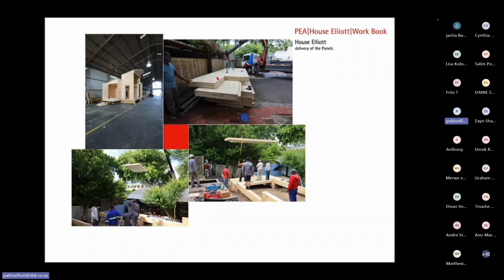So you can see here how the panels are laid crosswise in one direction and then the other. They are glued and put in a press, and they come out bonded together and are then cut up by a computer-controlled saw, to which Jamie fed my Archicad model, which he also had. They used the model to break the house into pieces. And then they fed these into the computer-controlled saw, which cut the pieces, even with their rebates and everything. And then they were delivered to site.